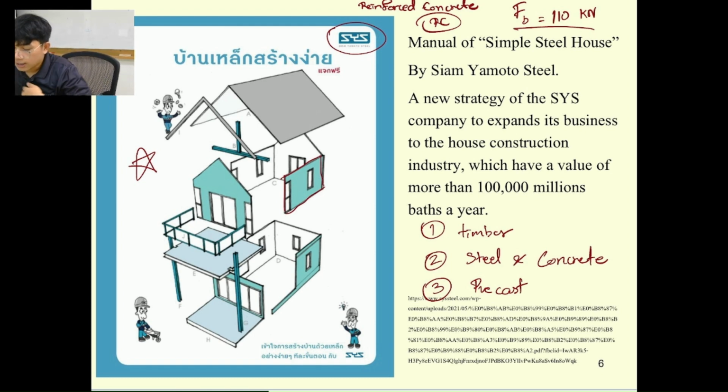But if you construct it by yourself, you need to prepare for the management, call for the concrete truck, and then cover it. Then you need to add some water for the curing at the site, and wait at least 7 to 14 days for it to gain strength until it reaches around 90% of the f'c that you designed.